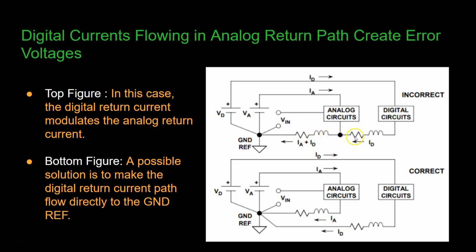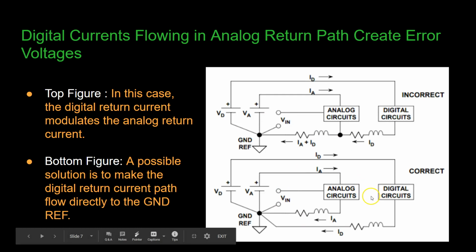And also the voltage drop across this here will be some, but if we consider over here, there will be a lot of voltage drop. So this is not a very good design. Instead of this design, we can use another design like this. And here you can see what change has been done. A separate path is provided here.